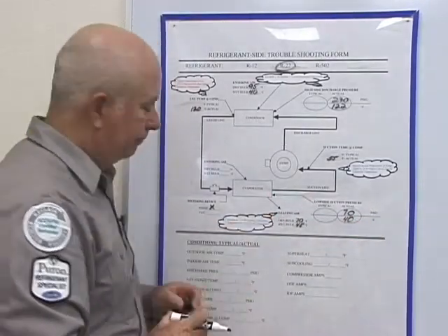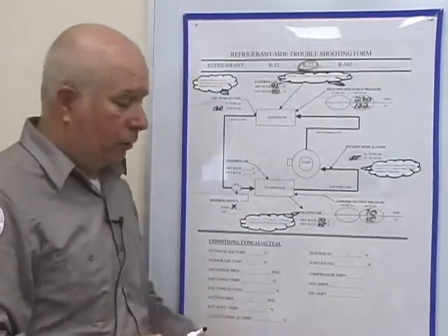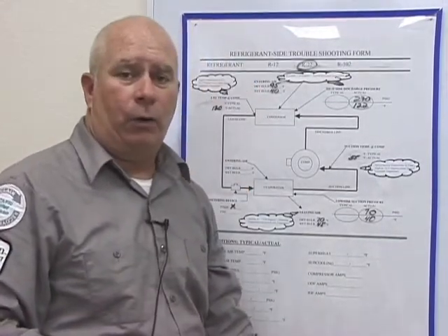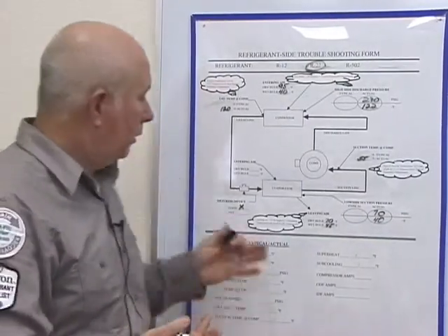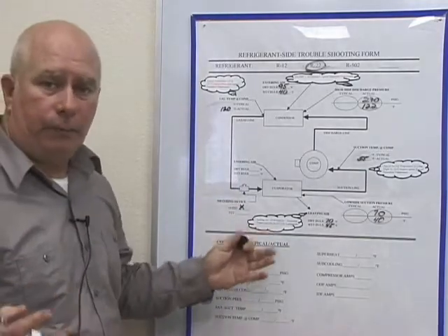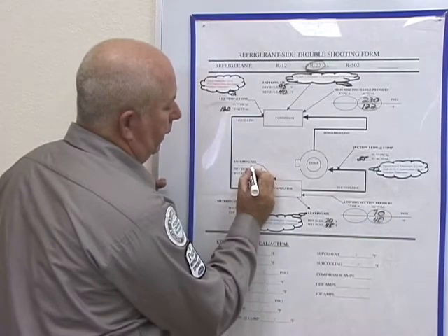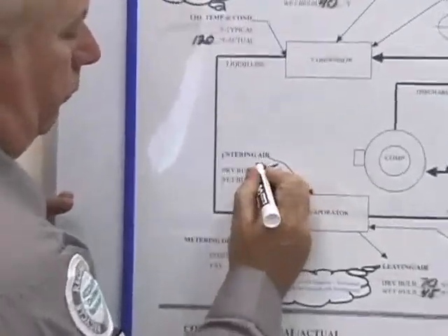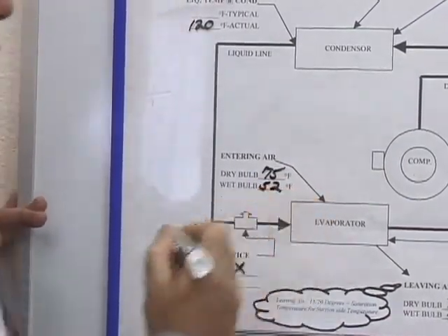That's the leaving air. The entering air is those registers or diffusers that are on the bottom of the floor, inlets near the unit, the air handler itself. It's returning the air, entering air, another name for return air. So that temperature, we'll say, is 75 degrees and a wet bulb of 52.